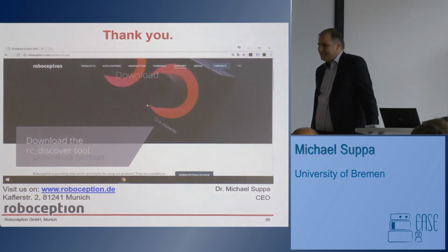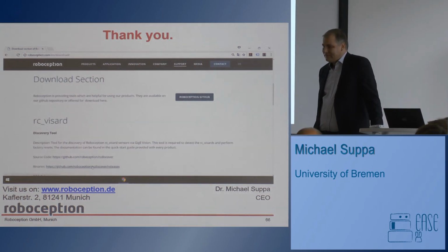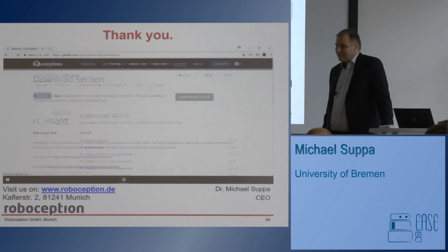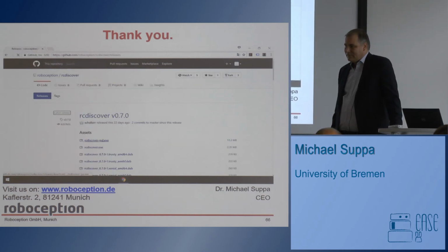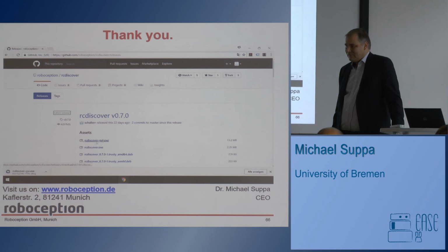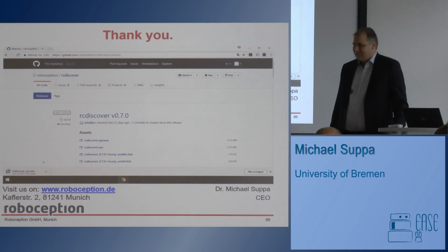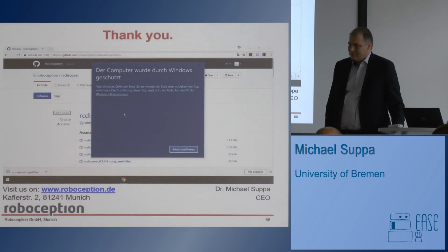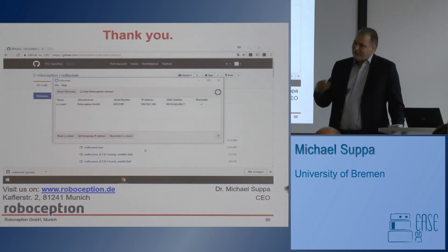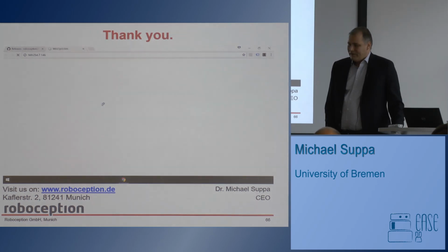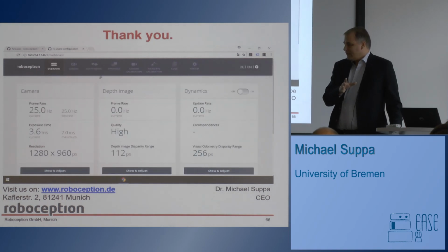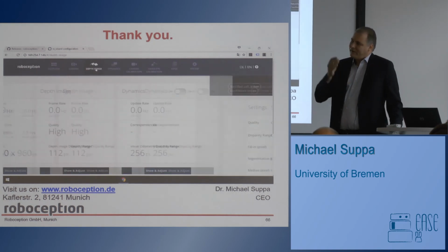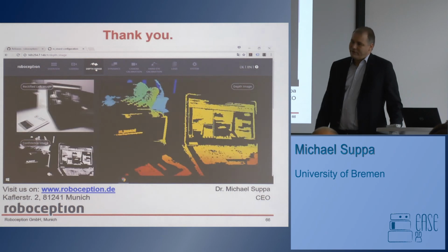Could you say a little bit about how you relate the real-world frame of reference, which is your calibration grid, with the robot frame of reference? They're different, and it's the robot frame of reference that you're interested in. How do you do that? So in most cases, it depends. If you have an external camera, then usually we place a calibration grid on the robot, on the end-effector, then we move the robot in 4 different positions.